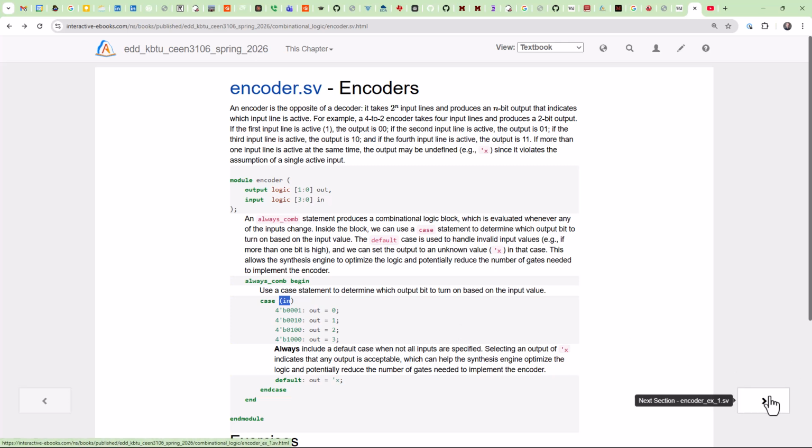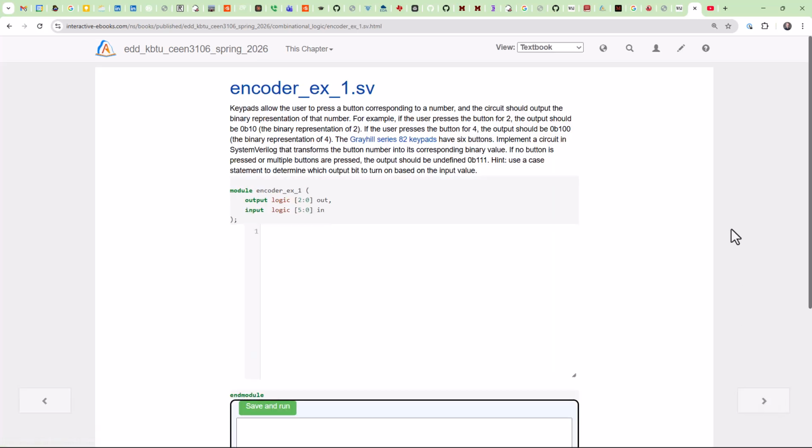Here again, in our first exercise, is simply a straightforward encoder. Use the standard case statement output. You can go ahead and define the output value. Of course, it's called out as 111 at the beginning of the case statement, or you could use the default statement, and then simply provide the appropriate series of cases that would allow us to determine the final value.